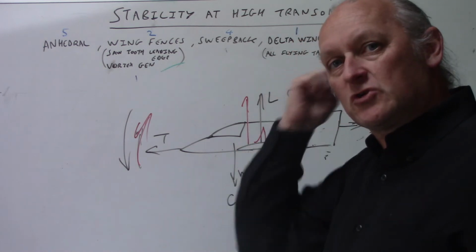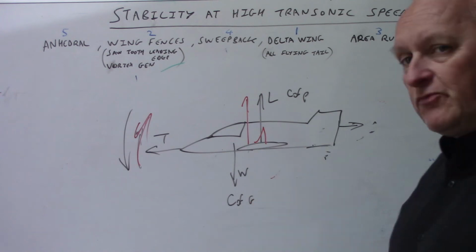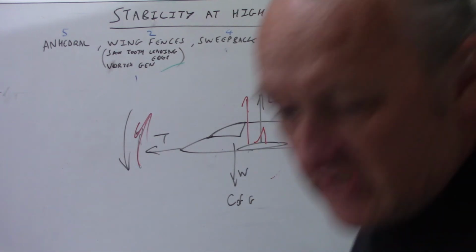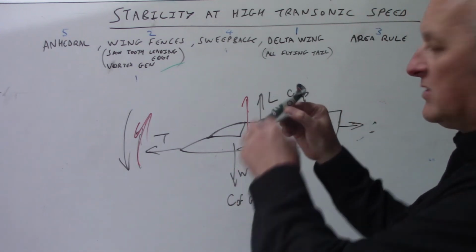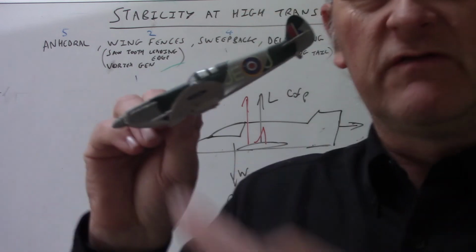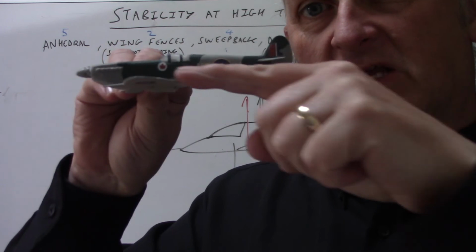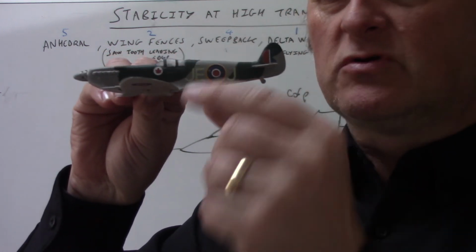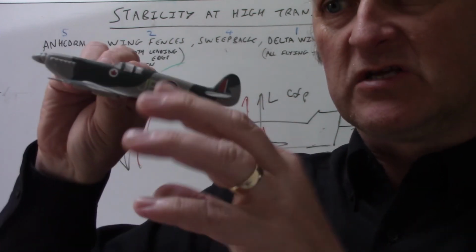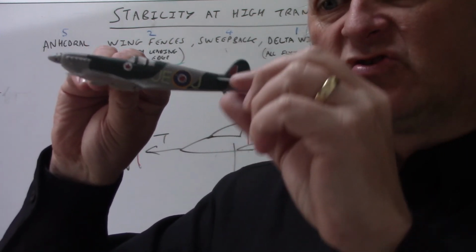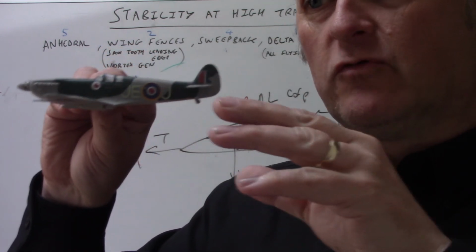The other problem that we're trying to solve is separated flow. Now, take your Spitfire: if you look where the wing is, and look where the tail is, quite low down, it's above the wing. People had worked out already that the turbulent flow on the back of the wing, when the aircraft was stalling and things like that, meant you need to have the tail higher so that the elevators didn't suffer from the turbulent flow coming off the back of the wing.